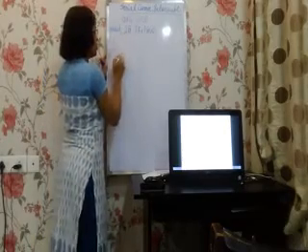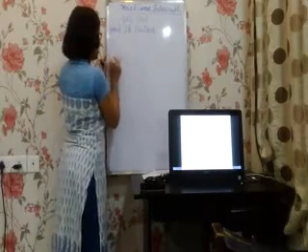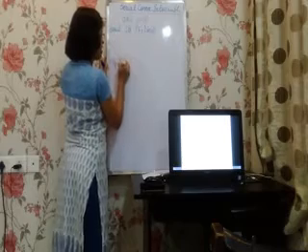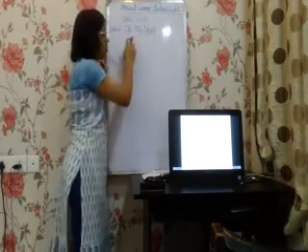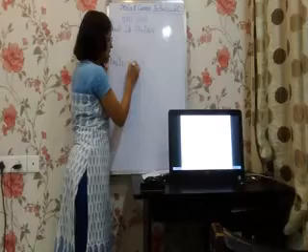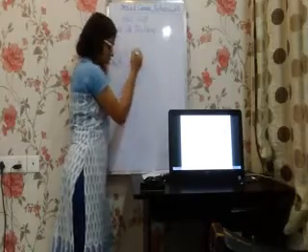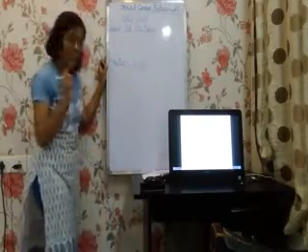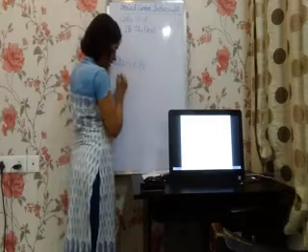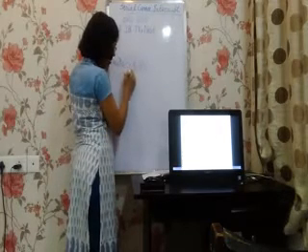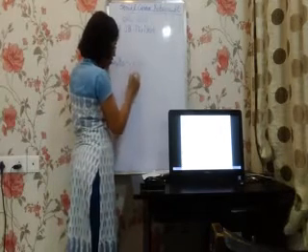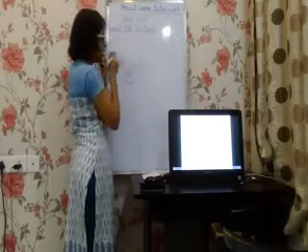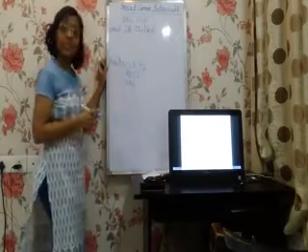So what I need to do? I need to come here, next, and what I need to do? TI flag is raised means clear TI. Clear TI, 8051 is working as a transmitter. Okay, clear TI and return followed by end. This means 8051 is working as a transmitter.